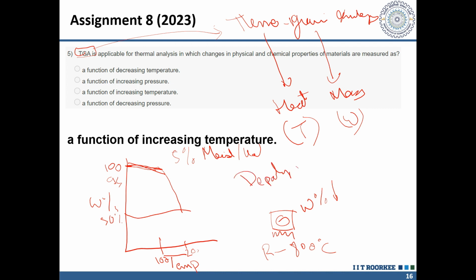then we can say that it might be due to the depolymerization of the biomass. Further, if there is a steeper decrease in the weight, then it might be due to thermal degradation. And at last, after 600 degrees Celsius, if there is some amount of biomass present that is not coming to zero, it came to 2% only and is constant at 2%, then it means that the biomass had 2% of inorganic compounds. So this is done by TGA.